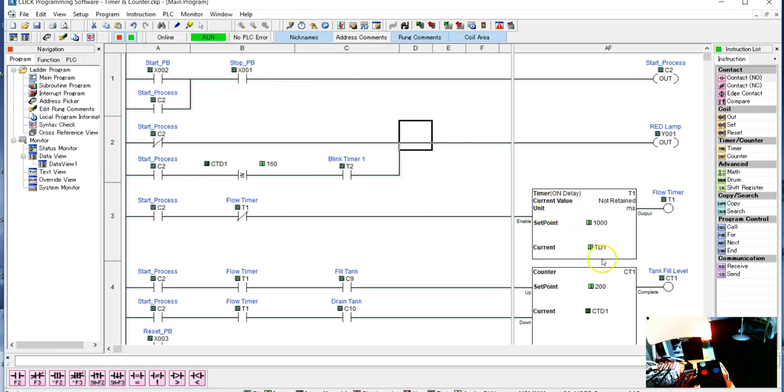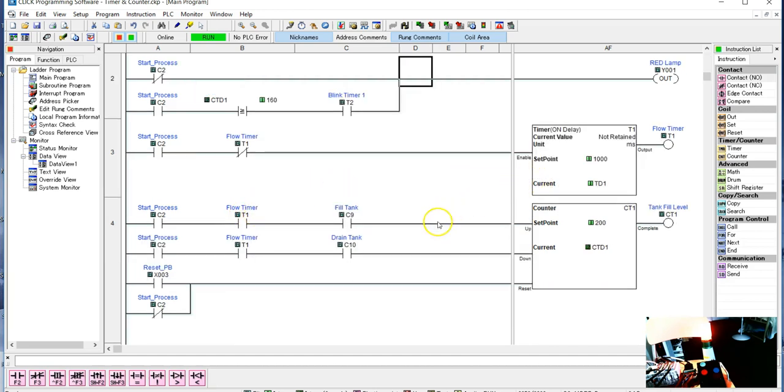We're going to just continuously run our counter, and this will reset it. Now every time it counts up to 1 second, it'll either be counting for filling, and it'll start out counting for filling. So it'll start at 0 and it'll go all the way up to 175, and then from there on it'll go down to 25 and back up to 175. And that's all this is going to do. Just keep going back and forth, back and forth. Here we can reset it with the push button, or when we're not on it, it'll be reset to 0, and that's fine.